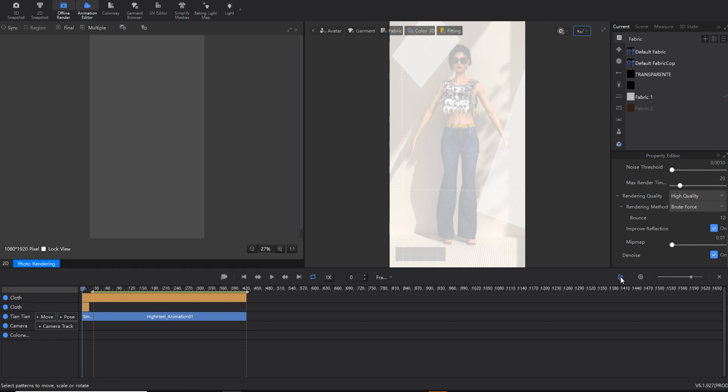And when you click on export right here, remember, well, that's what I like to do, I like to save the frames as images. I always leave this selected, because if your program crashes during exporting while rendering, you have the option to restart from where you stopped. It's going to save the frames in a folder, so you can go there, check the last frame that was rendered and start from there.